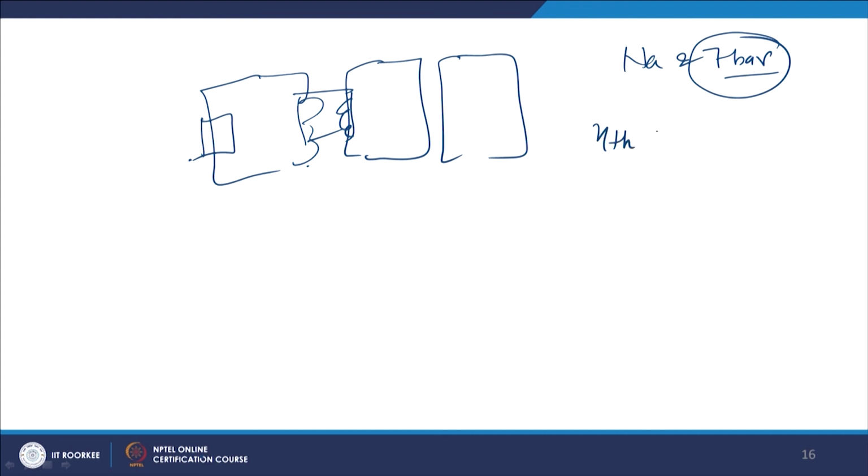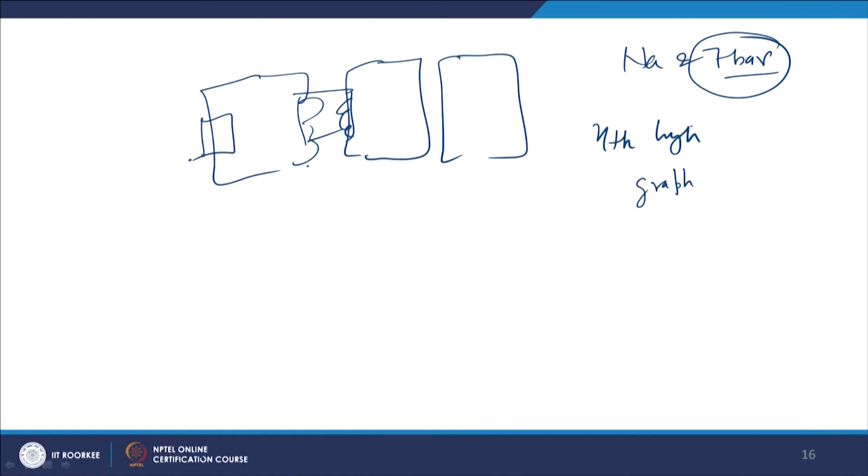Thermal efficiency is high. Definitely if a reactor is operating at a high temperature, the difference in source and sink is high. So, thermal efficiency is going to be high. And graphite moderator is used. Even low cost graphite moderator can be used in such type of reactor, and it is smaller in size. They are smaller in size, and superheating is possible in such type of reactor because they are operating at very high temperature.